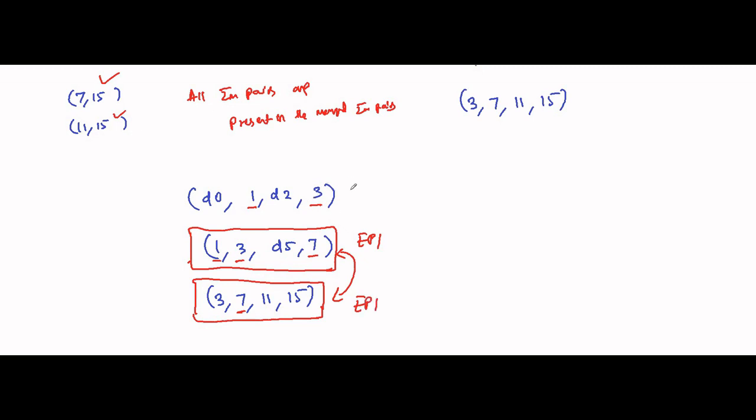This merged minterm pair is not required. Why? Because it has 2 don't care values which are not necessary to be included because they should not be given any priority, and the remaining 2 normal minterm values are already present here. 1, 3, they are already present here along with a normal minterm value. So there is no need to include this. These 2 are necessary.